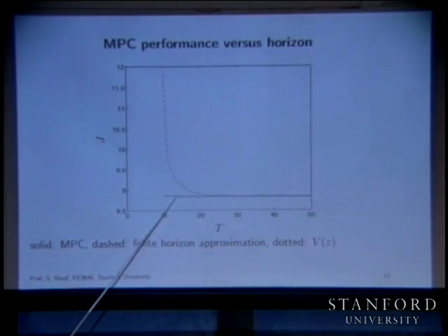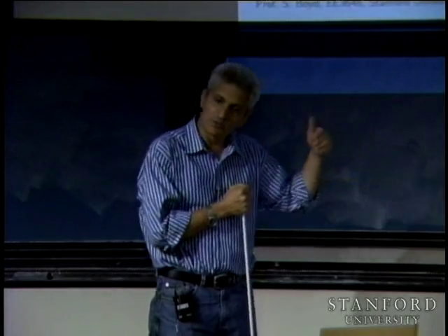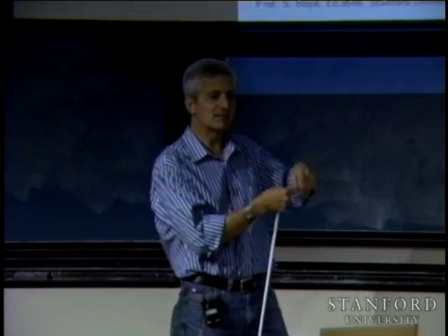So you're out here. I mean, you're basically doing flawlessly. At all times you're filing a plan of action to take the state to 0 in 12 steps. What happens at the next step? You then execute only the first input. You step forward, and now instead of saying it has to be 0 at that time, when it has to be 0 has shifted.